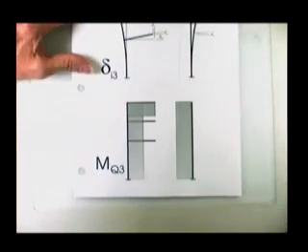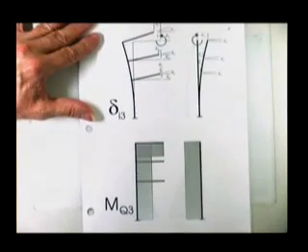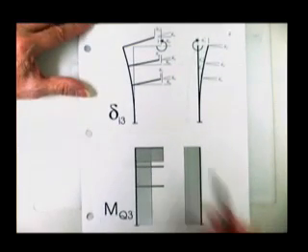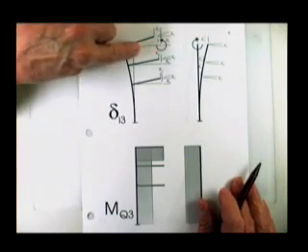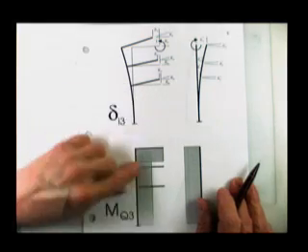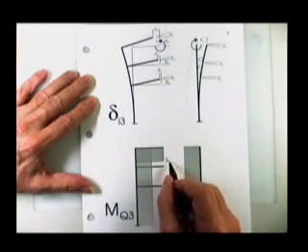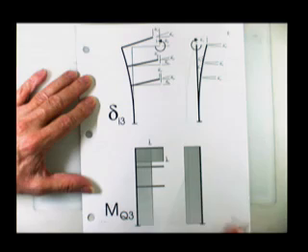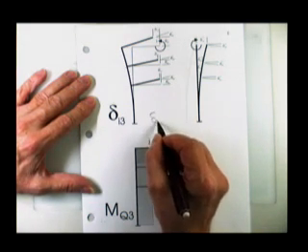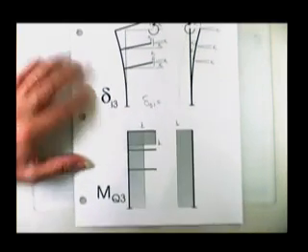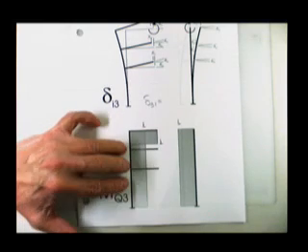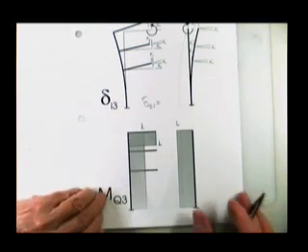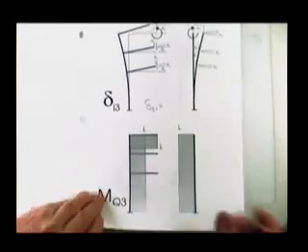There are your moment diagrams due to a unit load in the number 3 direction. That's a concentrated moment. Answer is 1, 1, 1, 1, 1, 1, 1, 1, 1, all the way down. That's a 1, that's a 1, and that's a 1. And if you want to get delta sub 3, 1, you would combine this one with the moment diagram that we had for the number 2 unit load. And here are all the rest of them.